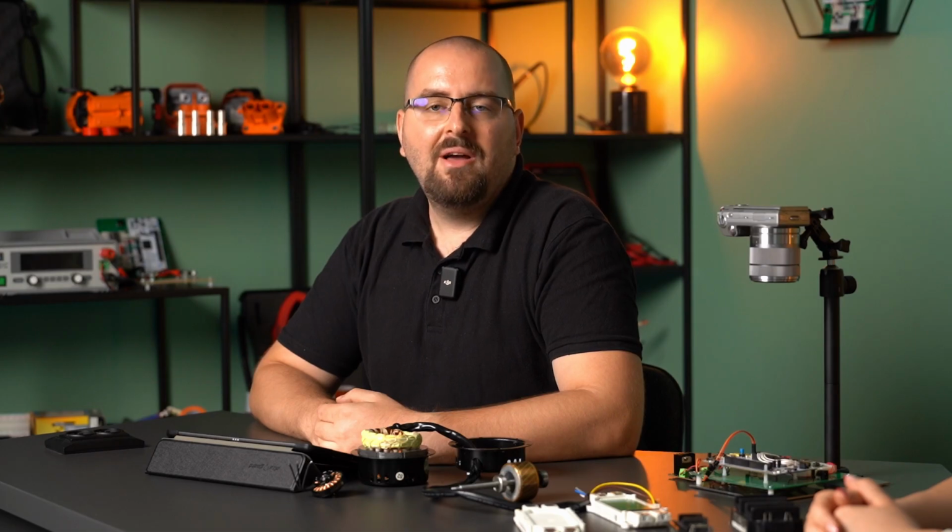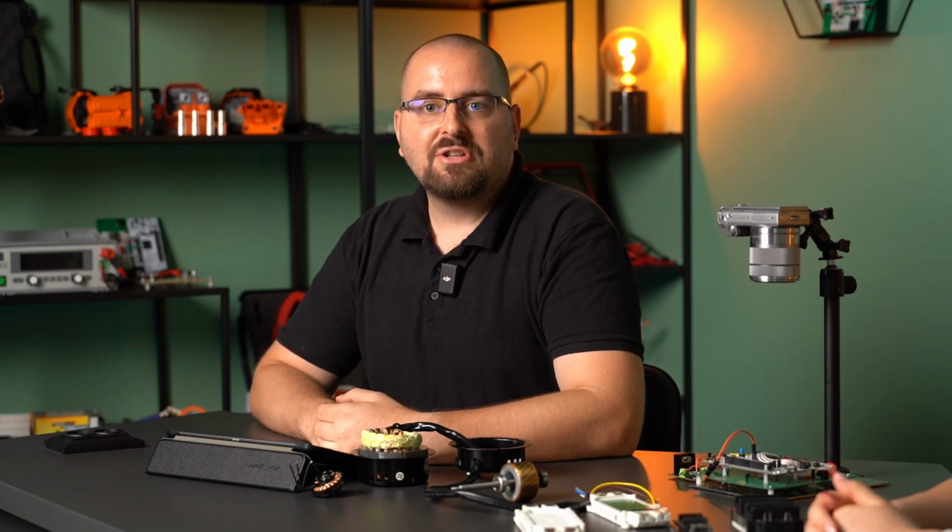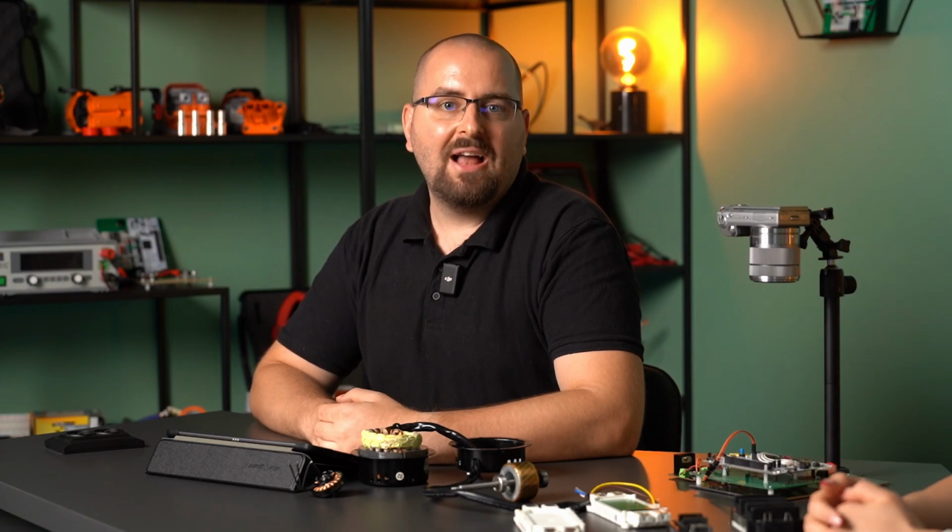This causes the rotor to have its own magnetic field, which interacts with the magnetic field of the stator to exert a torque on the rotor, so the motor starts to rotate. It's evident that the rotor of an asynchronous motor cannot rotate at the same speed as the rotating magnetic field of the stator, because then induction in the rotor would stop, and so would the torque.